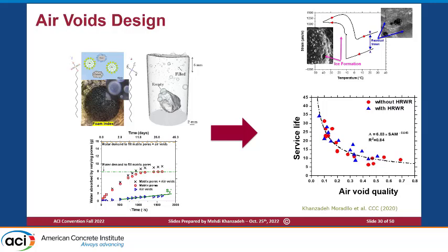life cycle estimate and see how air void quality, what I'm showing at the right side, impacts your service life against the freeze-thaw, right? So that's going to be a great help to account for the spacing, the permeability, and also the degree of the saturation of our system.